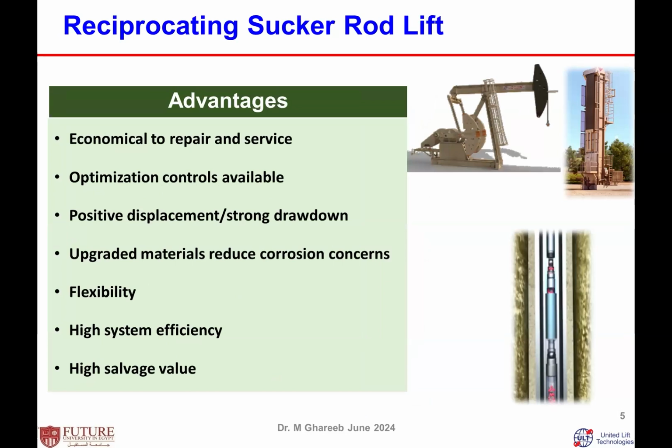Since it suits all types of applications, as I said, when you start to design and select your artificial lift system, and you find the rod lift system is capable of lifting your wells, then go ahead and use it. Why? Because it's very economical to repair and service. All the repair and service for this type of artificial lift is usually done in the field. You don't need to send your equipment to the supplier or the service company to repair. It's very easy and very cheap to repair.